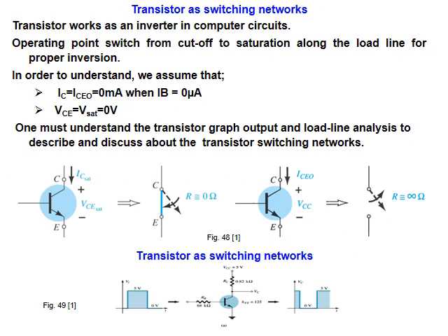For switching, now a transistor, as I mentioned, a BJT, could be used in the active region as an amplifier, as a variable resistance to amplify signals, or in the cutoff and saturation regions as a switch. This will be discussed in power electronics in level 3. But here I would like to mention that we deal with the transistor in the ideal situation as a wire when it is on, conducting the full current, and the drop is 0 because the resistance is approximately 0. This is ideally. And when it is open circuit, the voltage is high and the current is 0 because R is infinity.